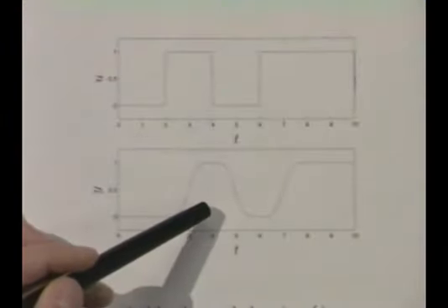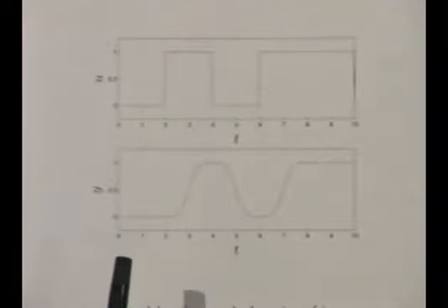His question was, could this really be the output of a system with this impulse response? The first thing you'd notice in describing this as the output is that it's been sharpened up considerably. And it's also been delayed by minus 1 second. In other words, whatever filter you have there would take a smooth signal, sharpen it up, and actually predict it 1 second in the future. This would cast considerable doubt on it. So you're absolutely right, except for the following. We'll go into that later. That's a good point.